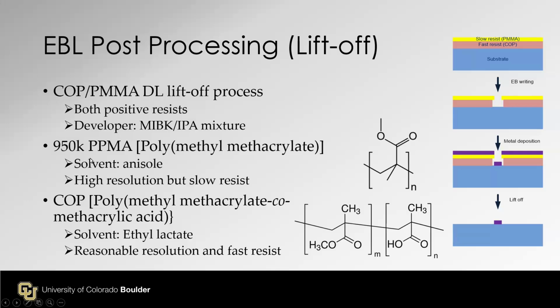So you want to pay attention to what kind of average molecular weight PMMA you are using. Okay, 950K or 1 million-ish is very good in terms of resolution. Line width would be very small, but it requires more dosage.